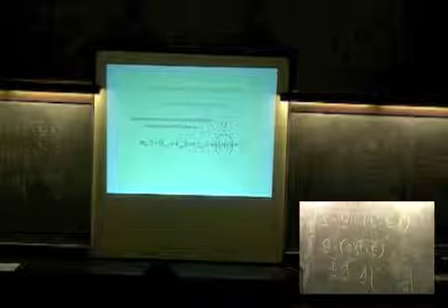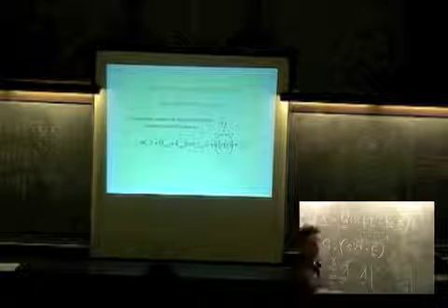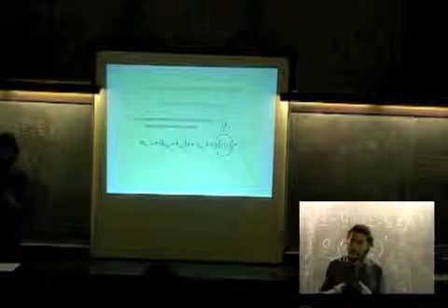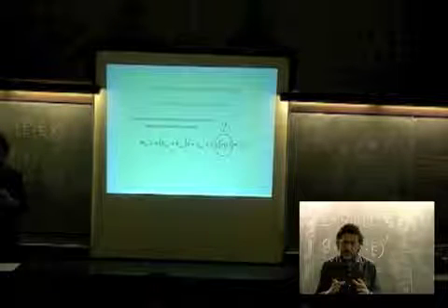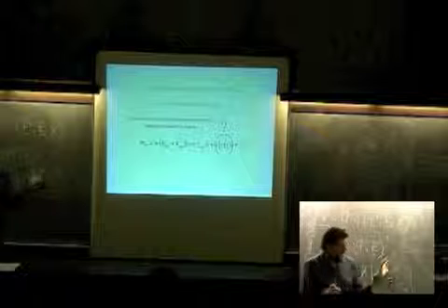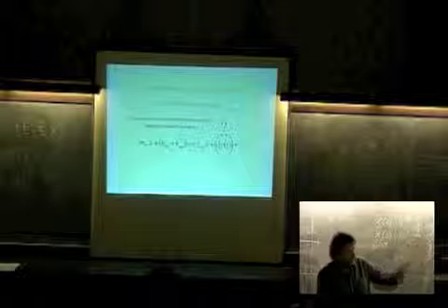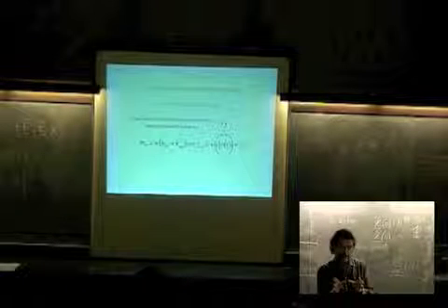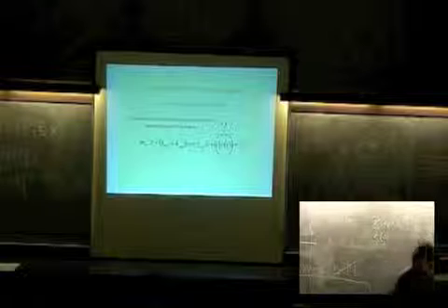One of the big requirements for this device that you have to mount on board is that, when they switch on the boosters of the rockets, you cannot use any kind of electrical device because it can interfere with the guidance system of the rocket. So you can only use passive systems in order to reduce vibrations on board. And this is a good example of a passive system that we can install on board in order to reduce the vibrations of the electronic package. I will show you some results about that.